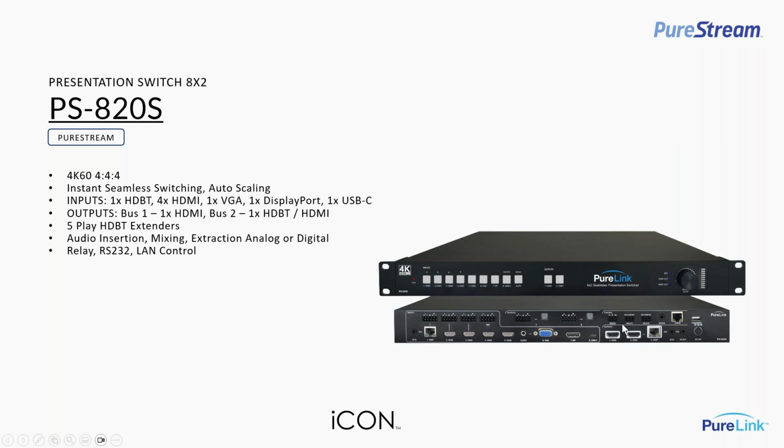Then you have some control capabilities. You've got LAN and RS-232 control of the switch, and then there's also the capability of entering information in the built-in web UI to set commands for the displays. So I can have, when this unit's turned on or off, I can have it control those displays. It also does CEC, so I can send CEC commands to those displays as well.